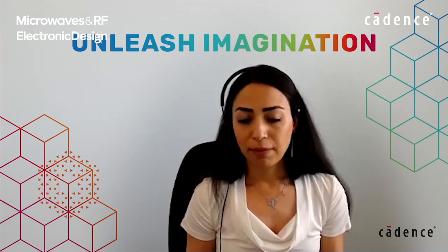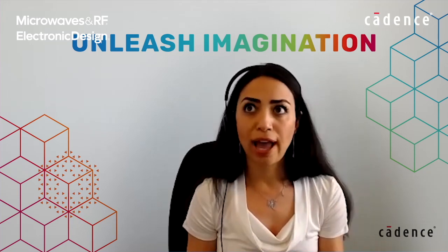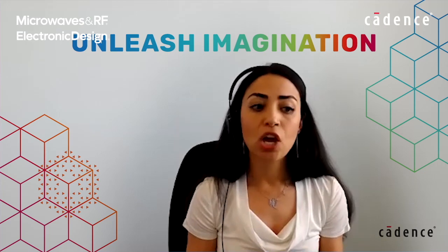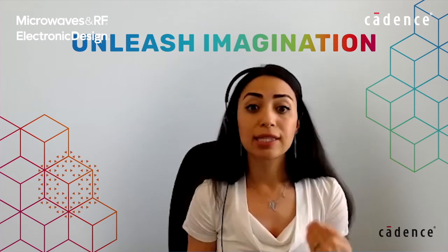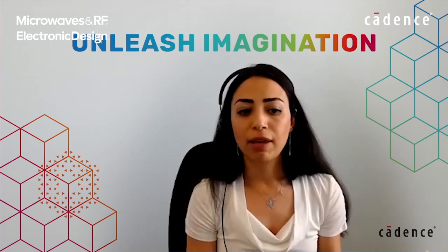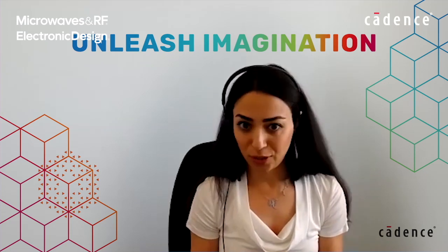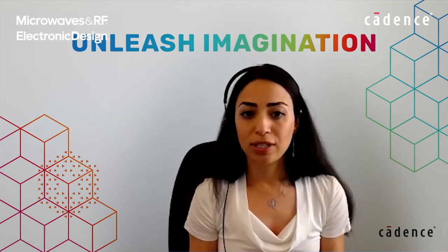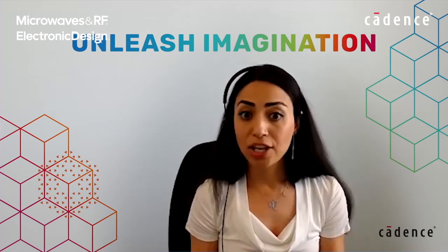Then, you come to package and PCB, and it's so important to have the detailed model. We used to have software that did not have the capacity to import the entire design for package or PCBs. But now it's a must, because thermal is a global problem. And imagine if you have to simplify your model, you will lose a lot of accuracy. So you don't know where your hotspots are. So that's why it's important to have the capacity in the tools that you can import both package, PCBs, and chip, and do a global thermal analysis to see where your hotspots are and address those.